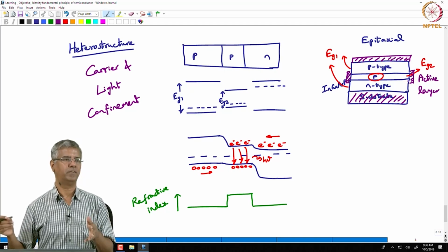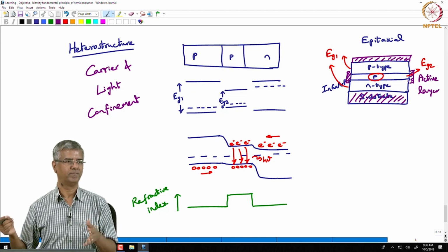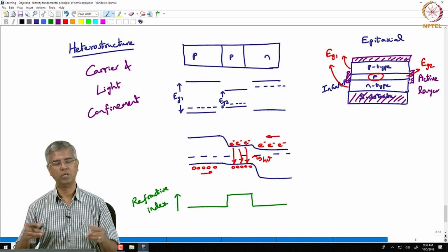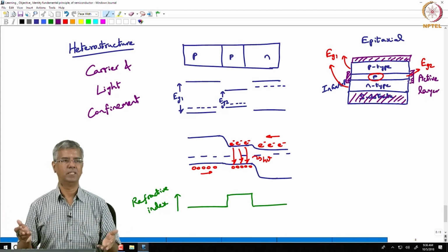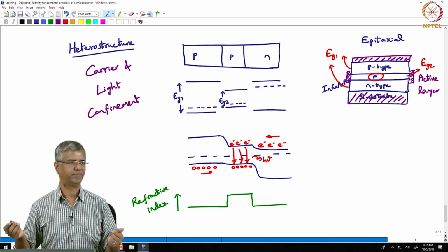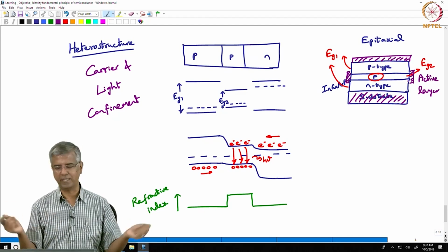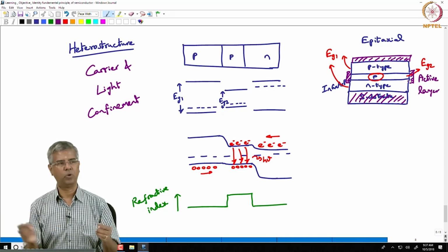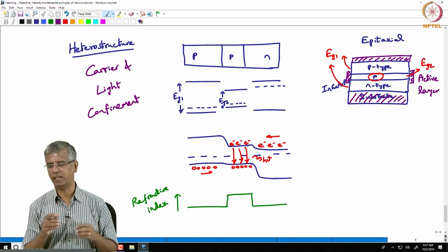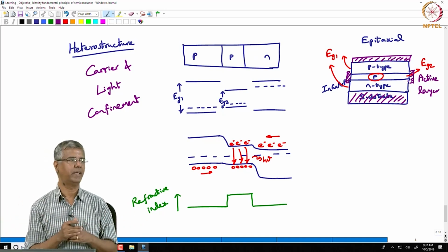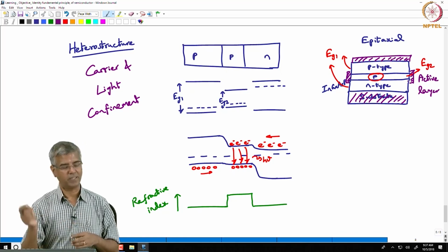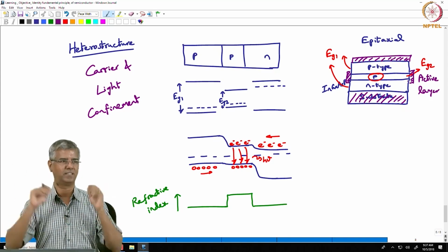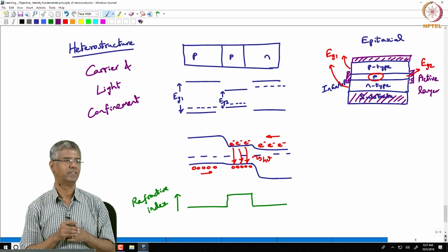So, what do you think the reflectivity is going to be? It's fairly high because of the huge contrast between the material and air. So, it naturally has about 30% reflectivity on either end. That 30% reflectivity can essentially bounce more photons within that active region, and you can easily make a laser out of this. So, if you are trying to make an LED, your biggest problem is that as you increase the current, it starts lasing, okay?